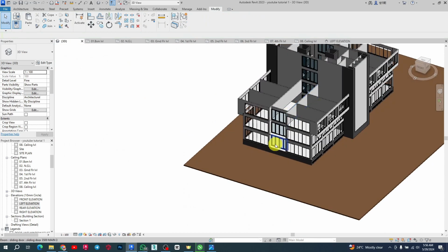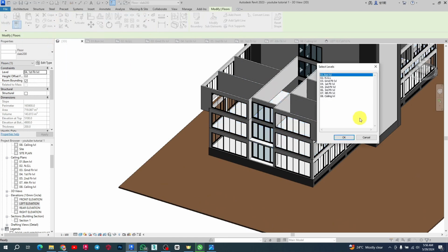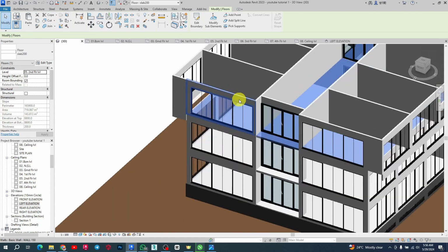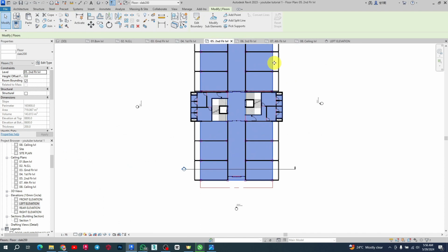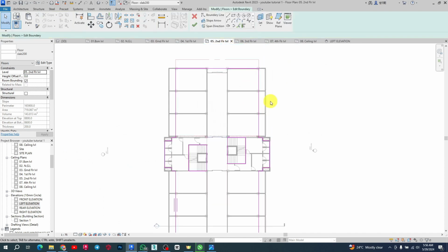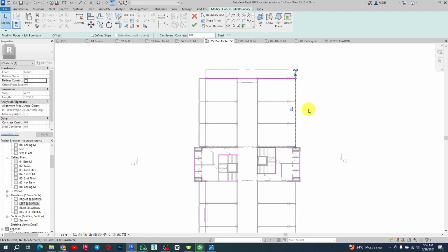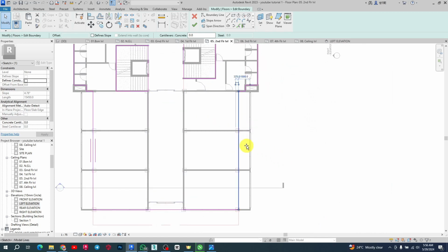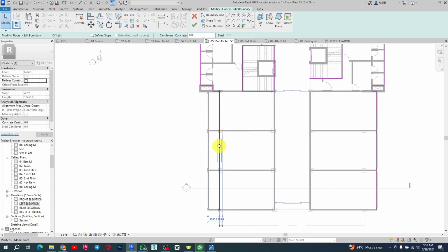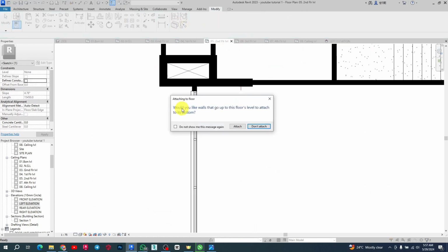Right? So I can copy this slab and just add to that level. So I'll just copy this before we go. So copy this and then align to second floor. Okay, so we have our slab here, but before then let's extend it real quick. So here, while it's still selected, I want to modify the edges, right? So I want to modify this edge from here to the center of this, right? Then from here to the center of this, from here to this center here, and from here to this center here. So that is it, and then I just hit finish.